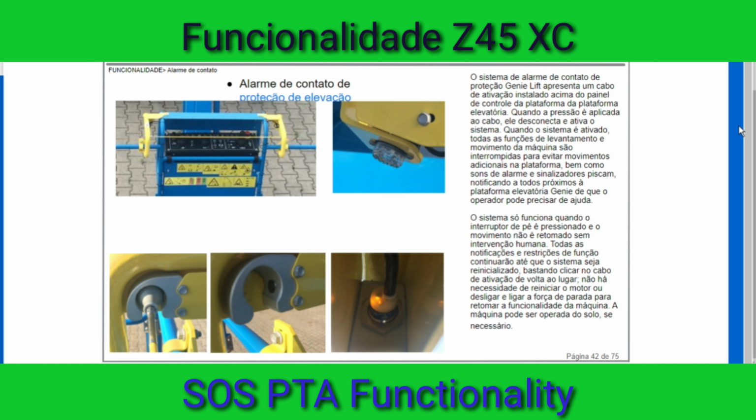The system is only functional when the foot switch is depressed and motion does not resume without human intervention. All notifications and function restrictions will continue until the system is reset by simply clicking the activation cable back into place. There is no need to restart the engine or to cycle e-stop power to resume the machine's functionality. The machine can be operated from the ground if necessary.